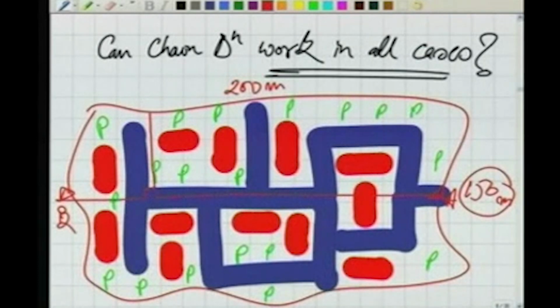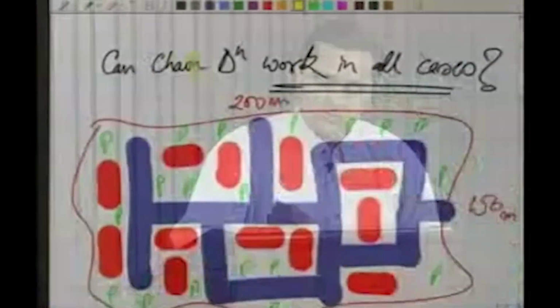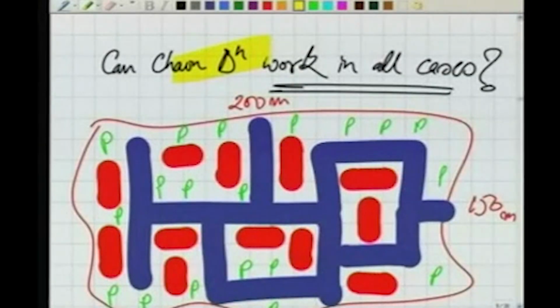Number two, another problem. If I need to measure an offset to this building, what will happen? This particular building is an obstruction here, because the buildings may be 1 story, 2 story. I am not supposed to climb over the building. So how to carry out the measurements? That's the problem. As we are talking about chain triangulation, can we use chain triangulation then?